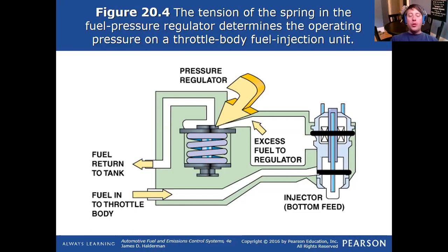And so fuel pressure regulators can be just your set spring style, where they just hold one set pressure all the time. They can be vacuum style, where they allow for a little bit of increase in pressure based on manifold load. And they can also be electronic. You saw electronic fuel pressure regulators incorporated into vehicles more in the last like 10 years.